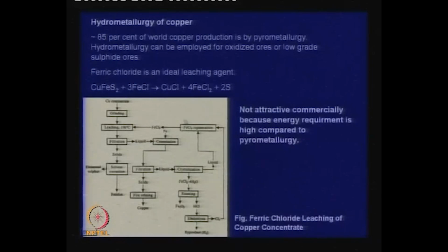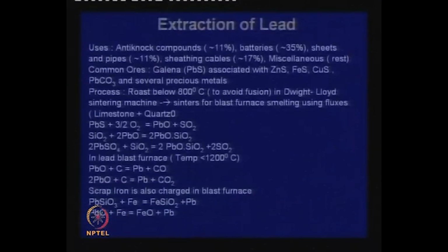We have talked about hydrometallurgy of copper, where the copper sulphide is roasted to copper oxide and taken into solution, and then once we have a solution we go for electrolysis and electrorefining. There is also bacterial leaching. In the case of copper ores, some bacteria help take copper into solution, but that takes a long time. It is ideally suited for low grade ores.